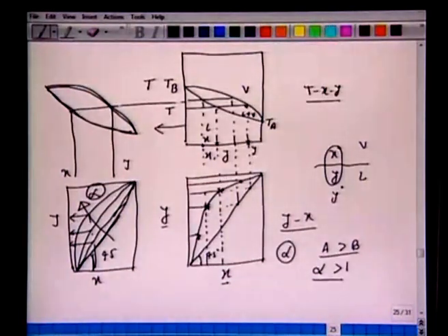So these are the things which we have to understand both physically and mathematically. We can write down all these Raoult's law equations. We can also write down the relative volatility expressions alpha to convince ourselves of the shape of the Txy diagram: the wider it is, the more separation. Here y is much larger than z_F, and z_F is much larger than x. And when we have very small relative volatility, these curves coincide or come closer, and we have very little separation. You can write down these equations for Raoult's law and do this kind of exercise. I leave this as an exercise; you must try to convince yourself.